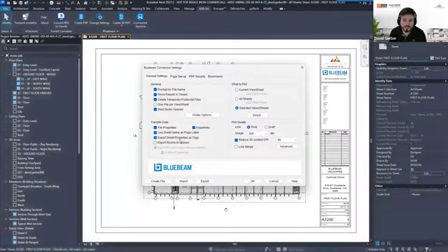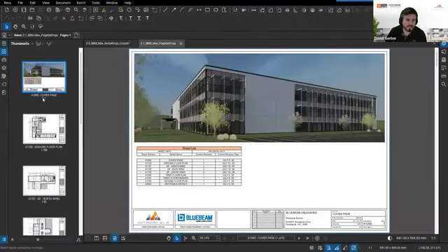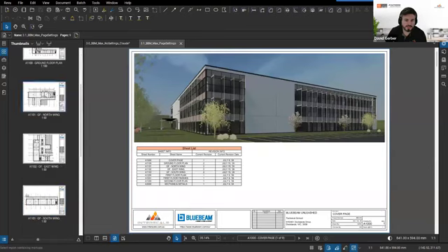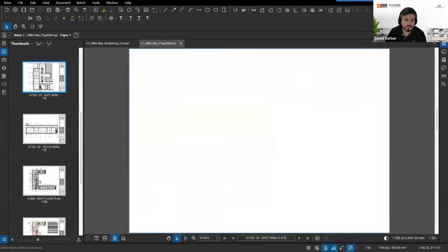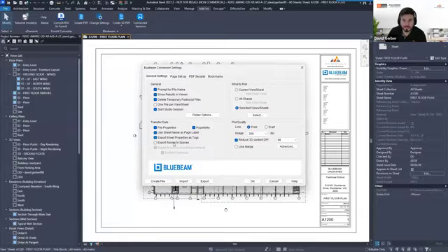With all my file properties, I can export the sheet names and their properties, which means when I go into Bluebeam, 2 seconds. Now I have my page settings, so I don't even have to create those labels. You can see it's already pulled out all that information. So Revit carries that over, which is really nice. So maybe I don't even have to do those page labels, or maybe if you want to change them.